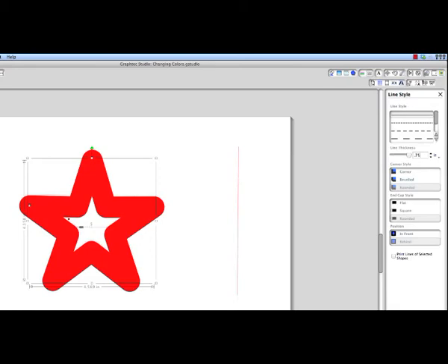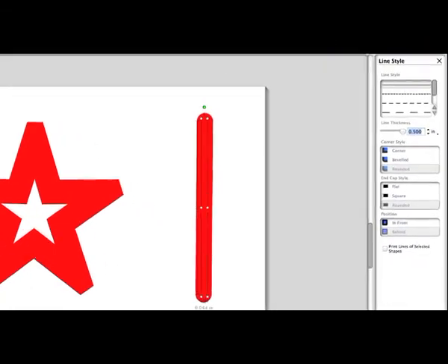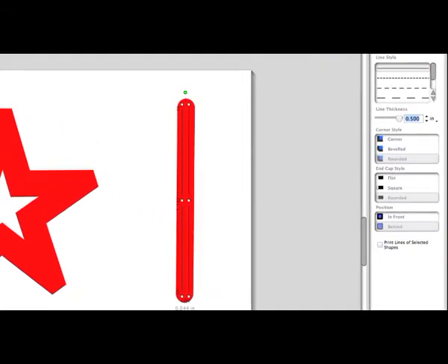The Corner Style option will adjust how lines appear at the corner points of an object. Corner is an acute angle of the two lines that make the corner, whereas Rounded will round out the corners. The End Cap Style option will only adjust lines that have open ends, whereas Flat provides a sharper flat edge at the line tip, and Rounded provides a smoother rounded edge to the line tip.